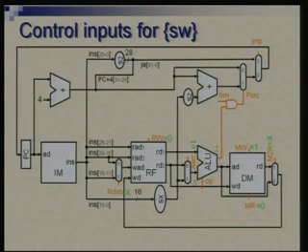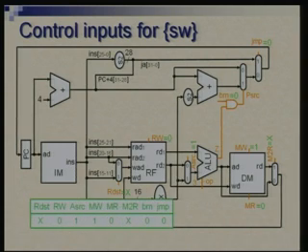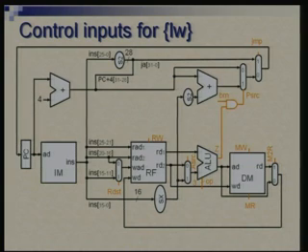Okay. So as you would be familiar with logic design, if there are don't cares in the specification, these could be exploited to simplify your circuit. Okay. So from that point of view, we will try to put X wherever we can, and further BRN is 0, JMP is 0. Putting all these together, we tabulate all the control signals which are required for this particular instruction. Next is the load instruction, similar exercise.